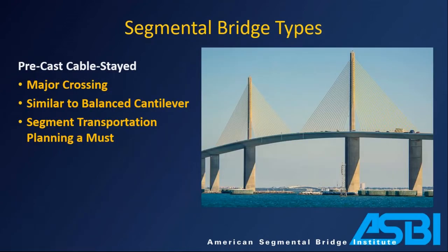Just like with cast in place, you can take precast and do cable stayed bridges with it here. Again, very similar concept, same construction. You're working your way out in cantilever and using the stays to handle those negative moments instead of the tendons.